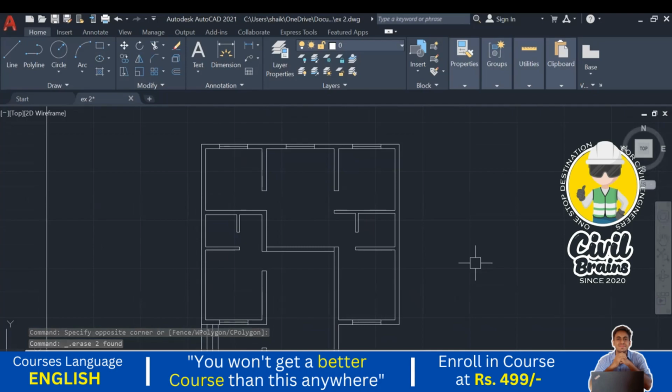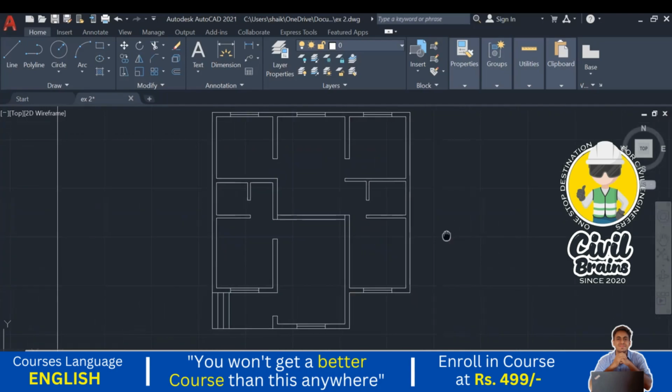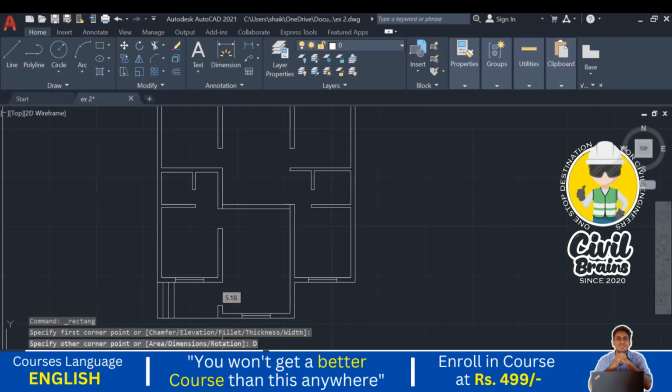Okay. So after the doors we have provided the windows. So walls also we have provided. Okay. So what is the next step? We just provide the ventilators. We just go to the ventilators. The dimensions of our ventilator are 0.6 by 0.5. Okay, 0.6 is the width of the ventilator. I just go to dimension 0.6, and what is the thickness? Same as wall thickness, 0.23.